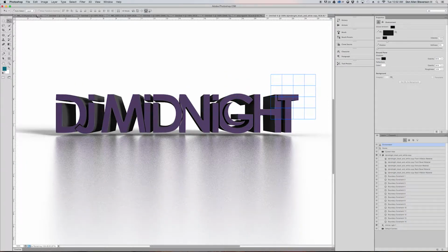So this animation is not rendered completely yet. It is still rendering. It does take a while. And I only stopped to interrupt because I want to say that adding shadows and adding reflections and softening shadows does increase the amount of time that it's going to take to render. What's nice is it increases the amount of realism with any of your three-dimensional edits, but consequently, it is going to take a lot longer to render. So I'm going to let it keep rendering out, and we'll be right back.